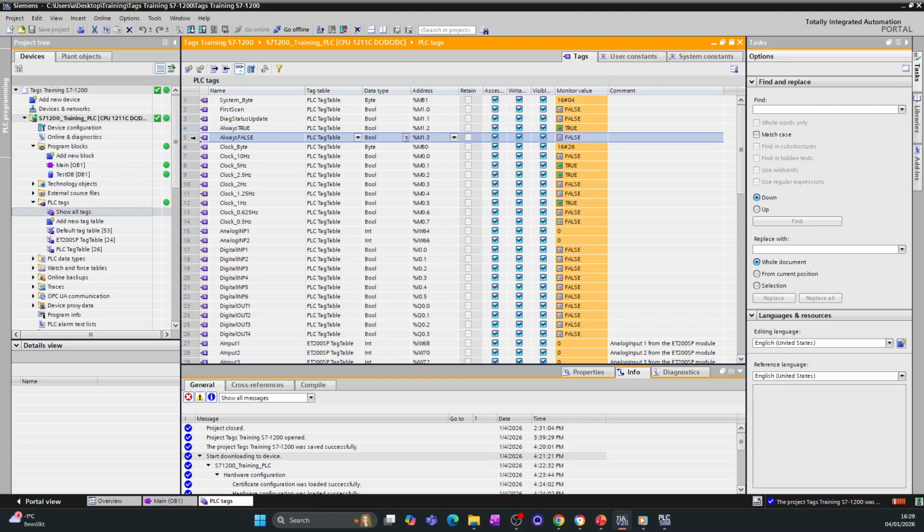If you want to set something to always be off, we can already use this to set it. The PLC is already doing that. We don't need to reprogram it. If we want something to switch at a clock of 10 Hertz, we already have this from the PLC. We have 10 Hertz, 5 Hertz, 2.5. Basically, they switch at different frequencies, and we can use that already. Instead of programming that by ourselves, we can use it. That's why I usually enable it.